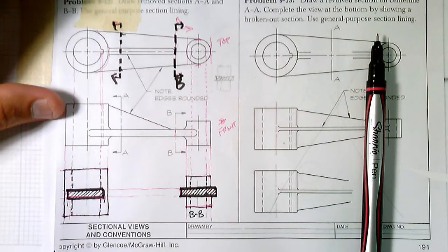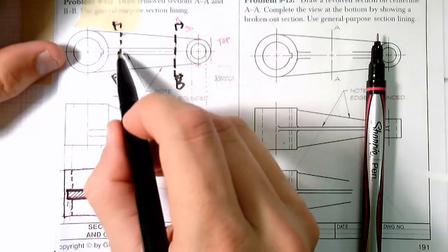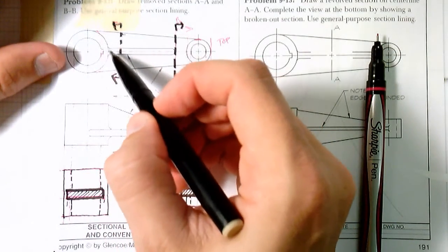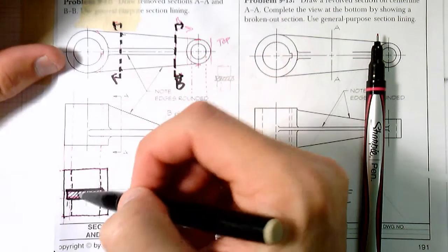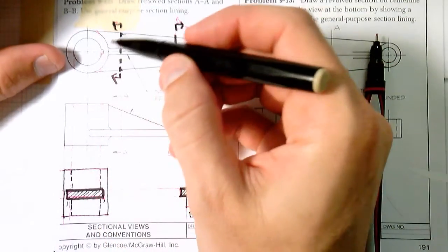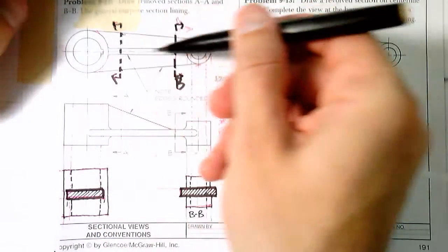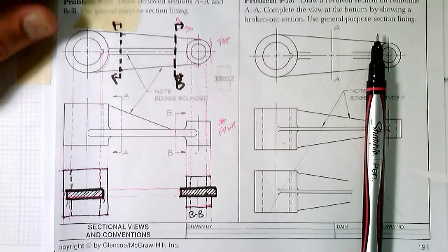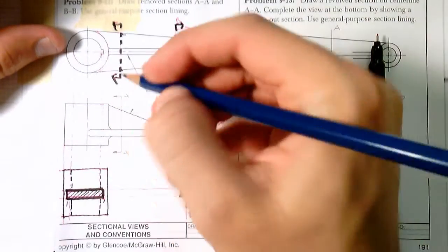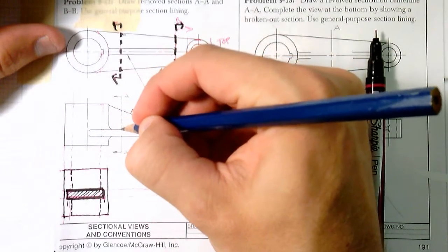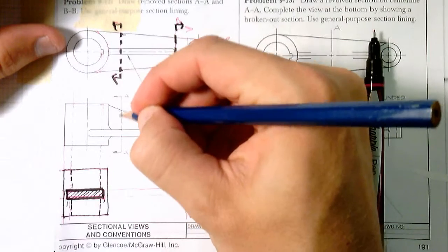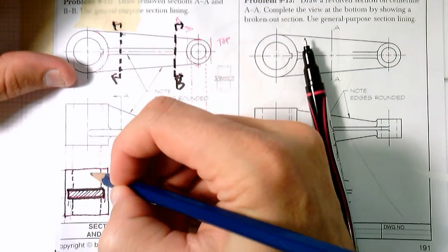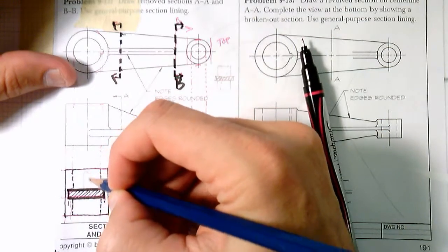Okay. Now the last thing you want to show, we can't forget about this rib, right? This piece that's popped up. But since this is just a thin rib, right, or it's cutting through this rib, we're going to show it and we're just going to cut through it because it's not cutting along the rib, it's cutting against the rib. So we will show that cut through. And in order to do that, we'll take a look at where A is right here, right? And you can see that zone is where we're cutting through. So if we took that information and we transferred it over here, it would be something like that, right?